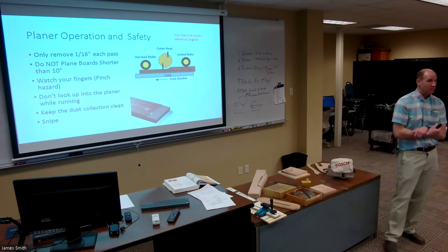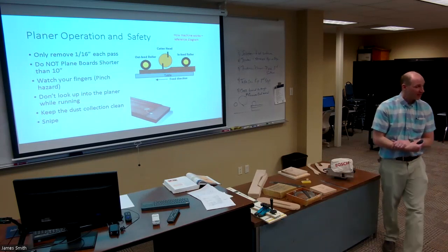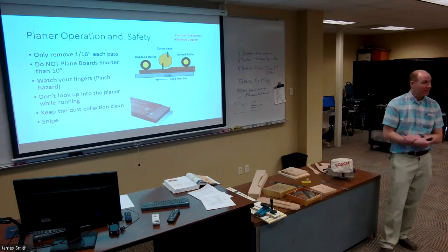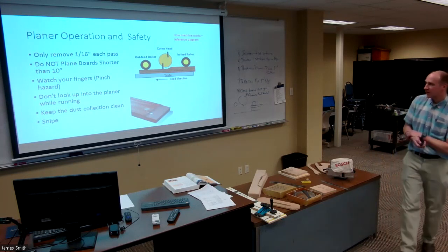So what do you do if you have a situation where your part is under 10 inches and you need to plane it down? You can put it in the vise and use a hand plane, or you can oftentimes glue them or use two-sided tape and glue them to another board that's maybe a little bit longer. There are some different ways of getting creative that way.